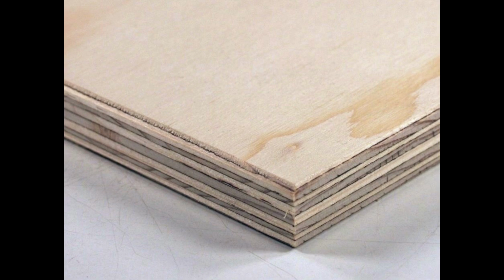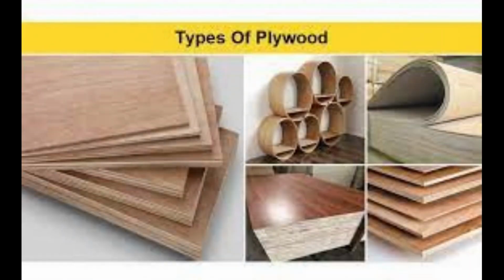Within Europe, basic plywood can be divided into 3 main categories. First is birch plywood, whose density is around 680 kg per meter cube. Secondly, mixed plywood with a density of 620 kg per meter cube. And the third, conifer plywoods, whose density is around 460 to 520 kg per meter cube. Different varieties of plywood exist for different applications nowadays.